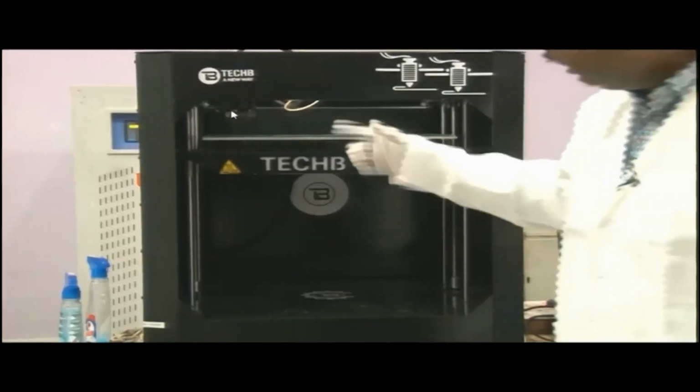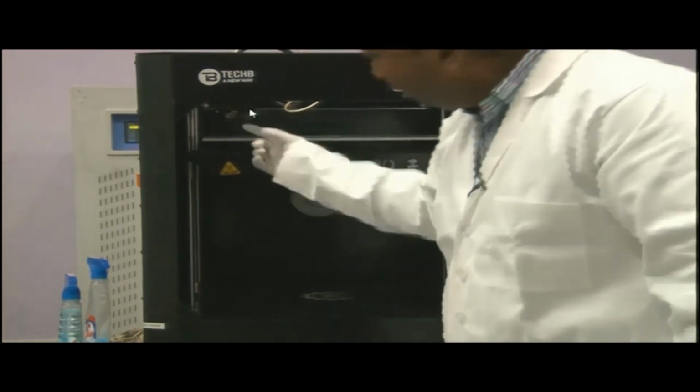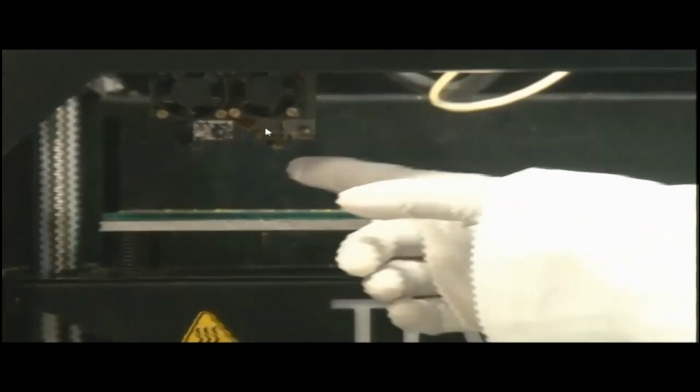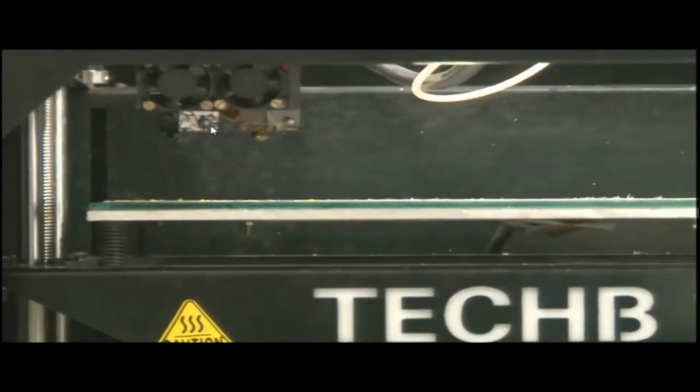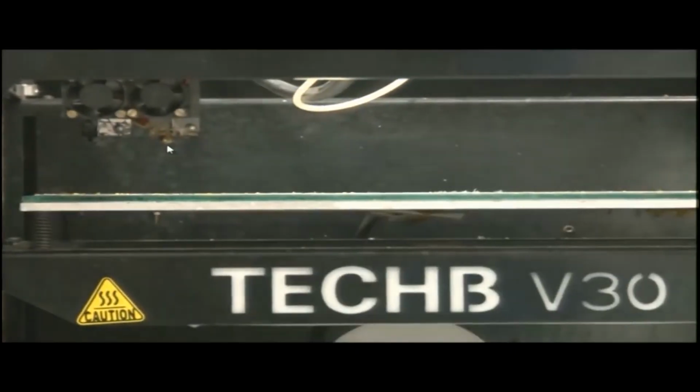Now this portion is known as the head, where the nozzles are attached. So the material is fused and comes out from these nozzles. There are two nozzles here, nozzle A and nozzle B. Why are two nozzles there? We'll explain. One nozzle is for the base material, another is for support. This is a very fine orifice. The orifice diameter of the nozzle is 0.4 mm.